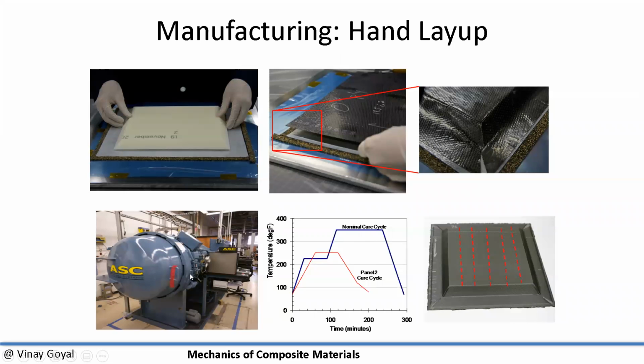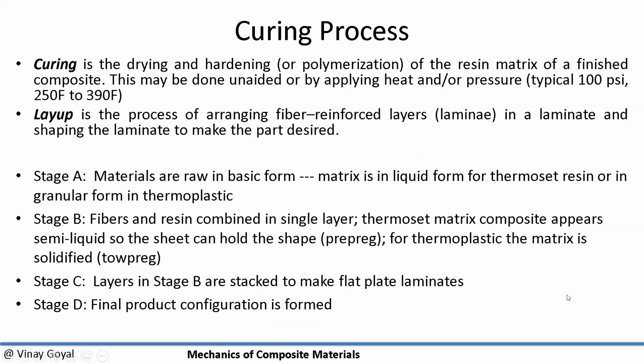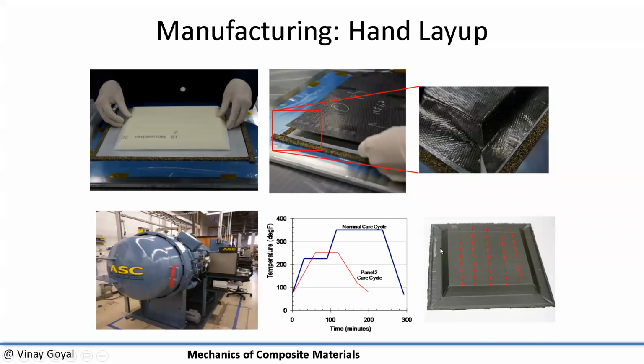And then we put this in the autoclave, running through a profile that has been predetermined by a lot of studies, either provided by the supplier of the materials, or you received them from the supplier. And now you're verifying that the performance of the materials is up to par using the curing cycle. Once done, we cut it up. And once cut up, we can inspect them first, or we can inspect them at this point in time.